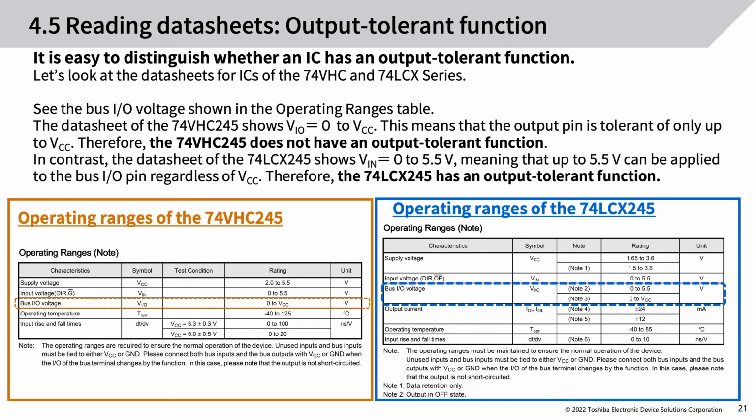In contrast, the datasheet of the 74LCX245 shows VI/O equals 0 to 5.5 volts, meaning that up to 5.5 volts can be applied to the bus I/O pin regardless of VCC. Therefore, the 74LCX245 has an output tolerant function.